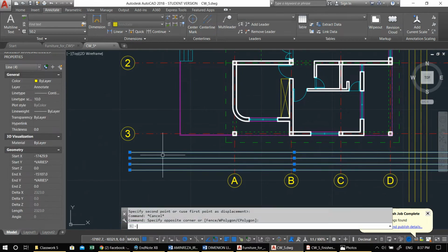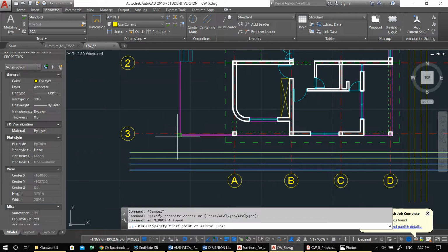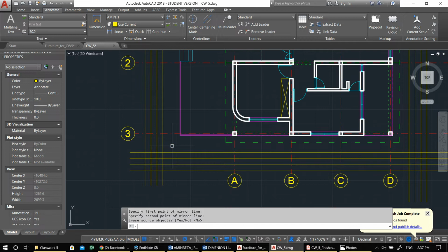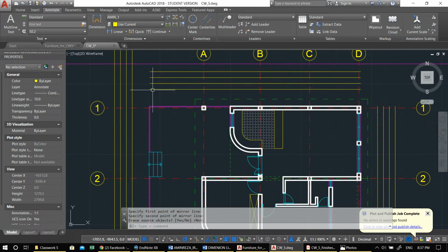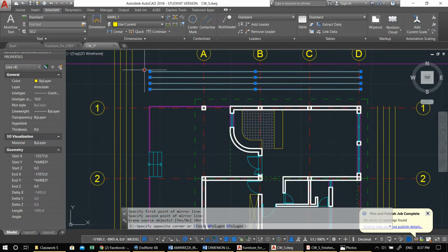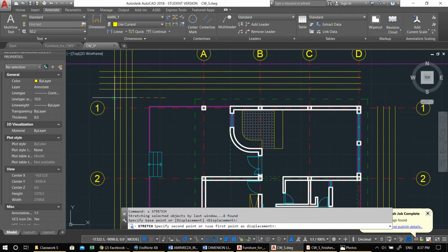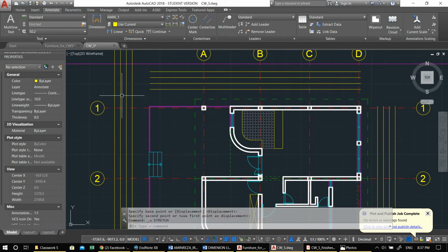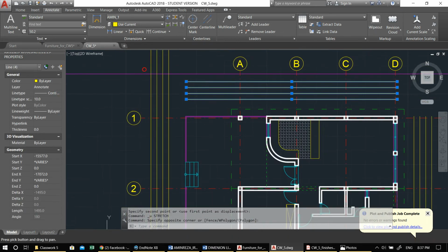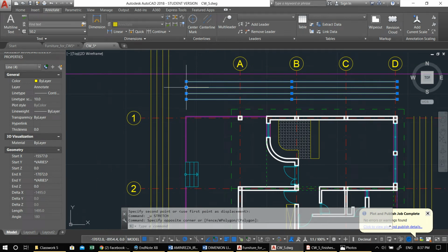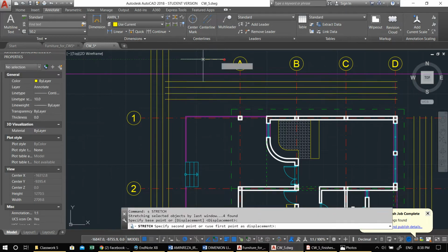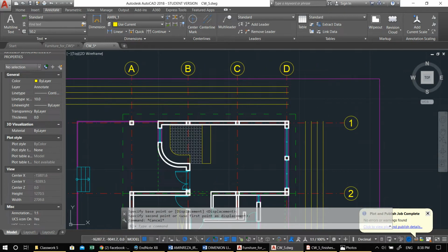And then here, MI, because you want to have dimension lines in standard technical drawing, in all 4 sides. Pick the head of the line, stretch, like go out. Oh, I made a mistake. This is the downfall of using polar tracking sometimes. Stretch. Pick head of the line, S enter, and just push it up. Okay, now